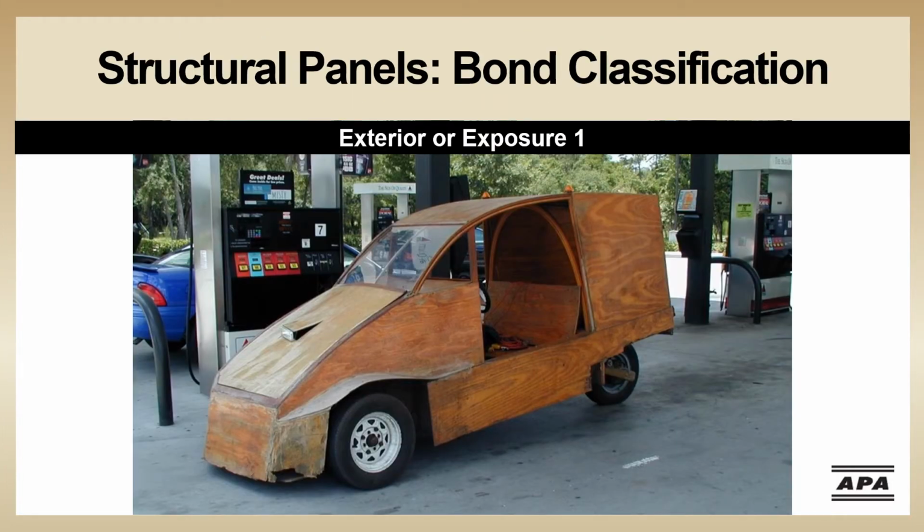So our first test question of the day: what bond classification of plywood should be used in the manufacturing of this over-the-road vehicle? And obviously the answer is exterior, because you're going to be consistently exposed to the elements.